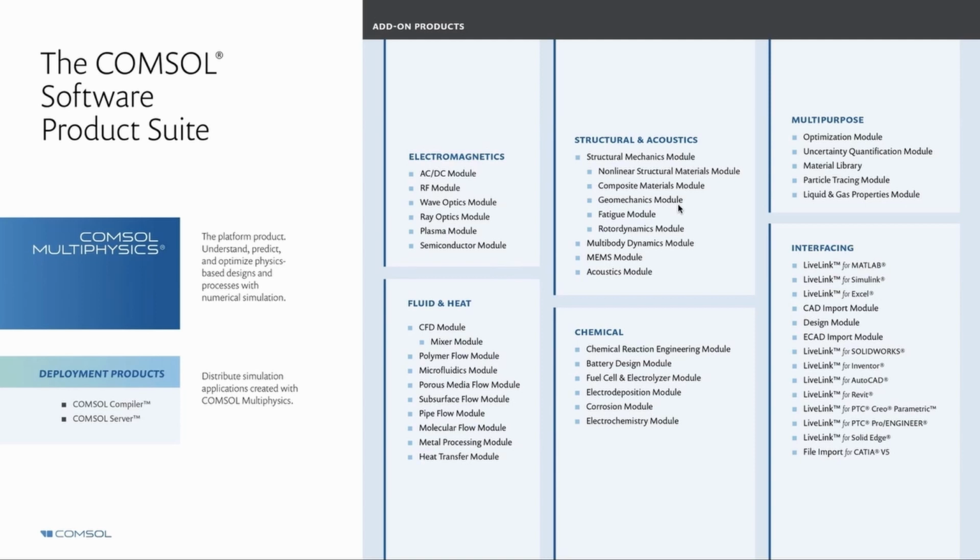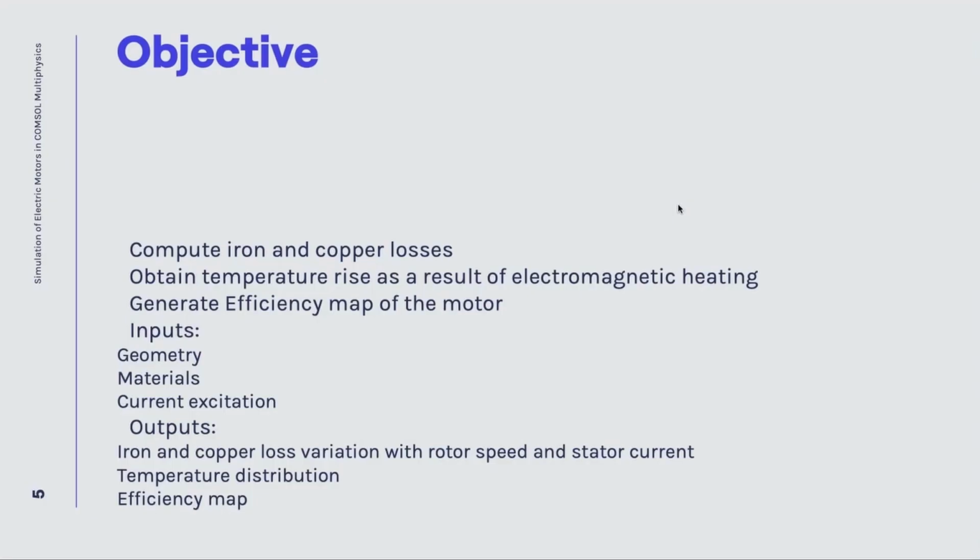If you want a high fidelity model, like a finite element model of your electric motor with all the proper physics setup, then you can attach this model in a co-simulation manner with Simulink, build the controller part there, and do the co-simulation within the Simulink interface. That's a very brief introduction to what you can do with COMSOL Multiphysics.